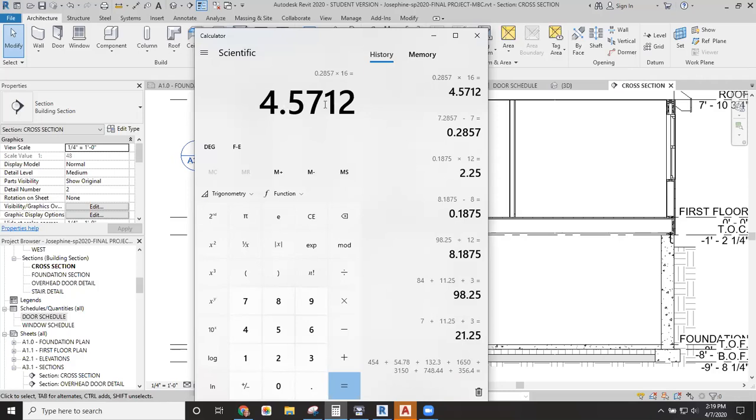If you draw this in AutoCAD, you'll see how I use divide to automatically have the risers be divided perfectly. It goes out this many decimal places. But when I actually put my dimension on it, I round all my dimensions to the nearest 16th, and it gives me those dimensions automatically. Okay, cool. Yep. Thank you.